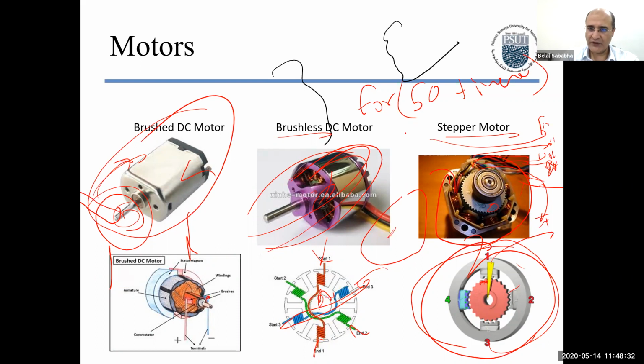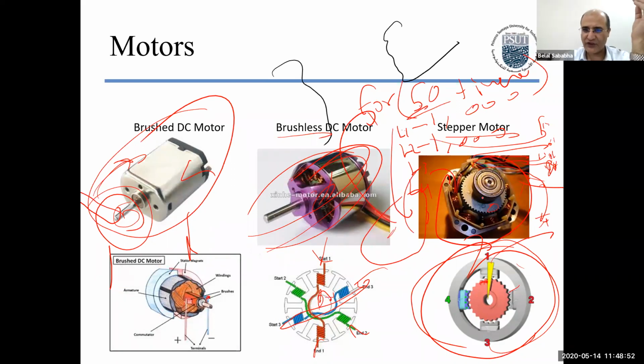So put on line 1 a 1 and everything else zeros, and then on line 2 put a 1 and everything else zeros, then line 3, then line 4, activate it, and repeat this 50 times. So we've moved 4 steps here, times 50, this is 200 steps. So you have a full rotation.